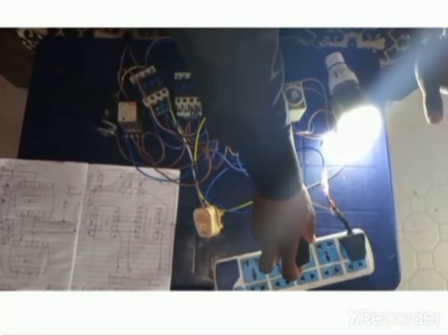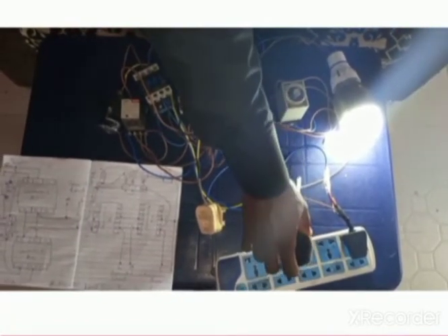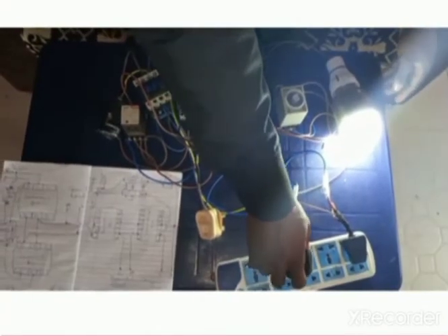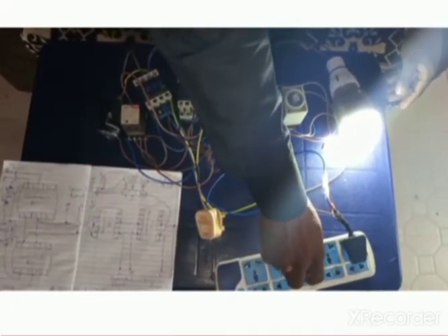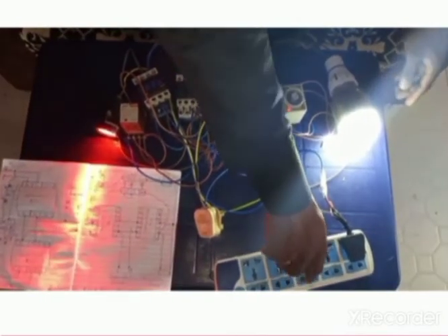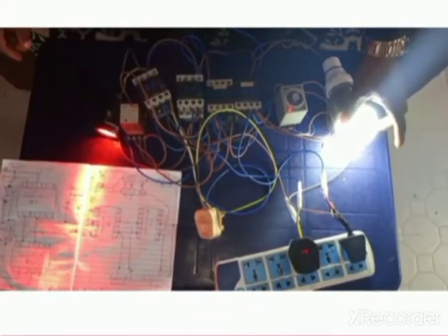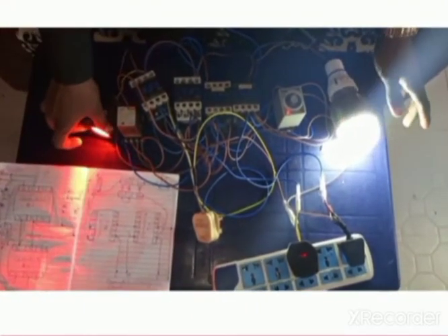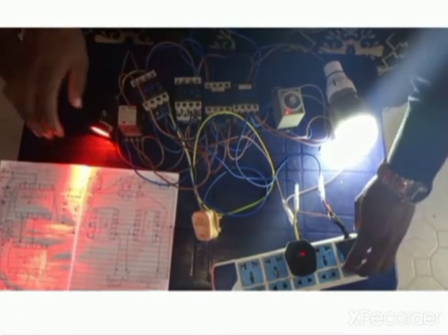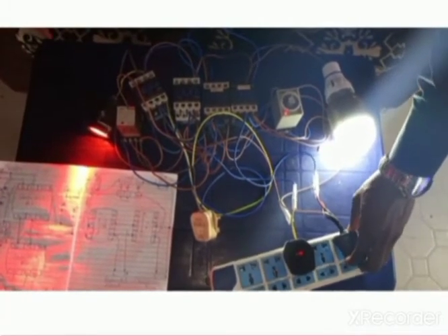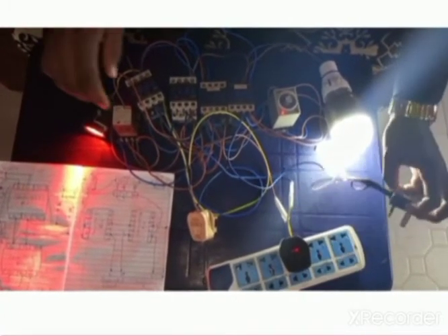But when you use the generator, it will automatically switch both the general load and the separated load, just like this. You see that the separated load and the general load are on for the generator. So even if you remove this one, nothing happens, because there's no supply at the inverter side.